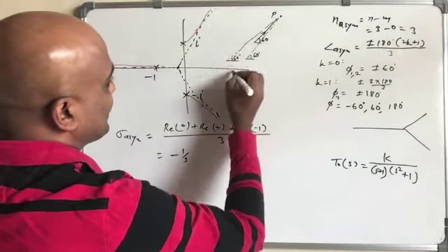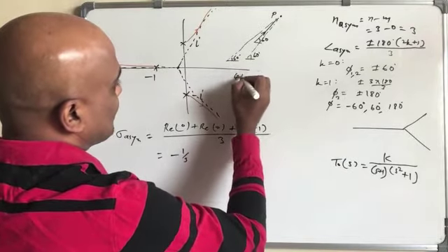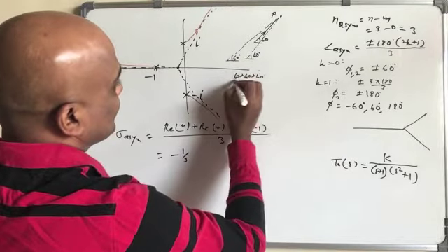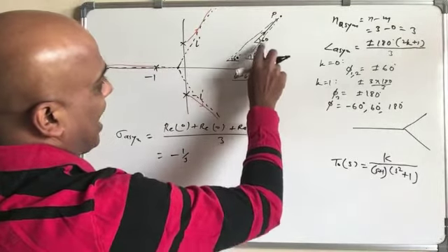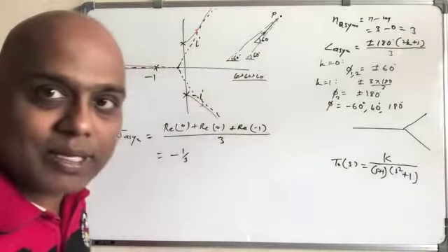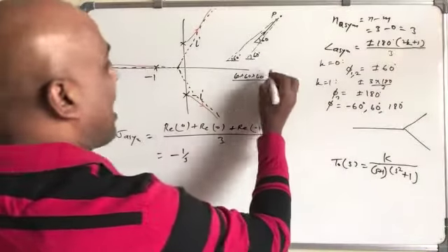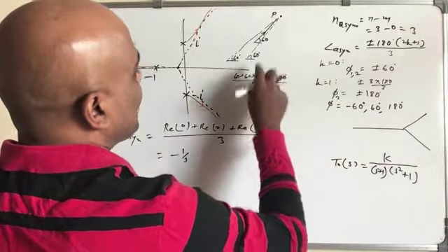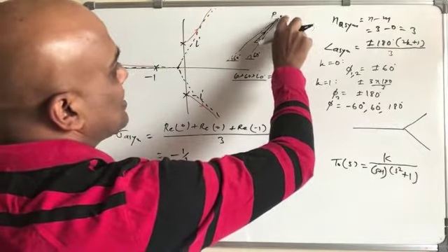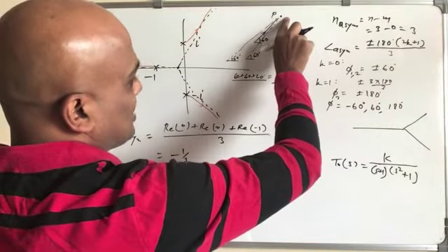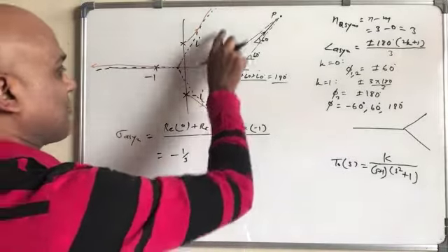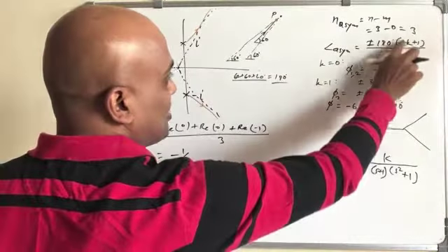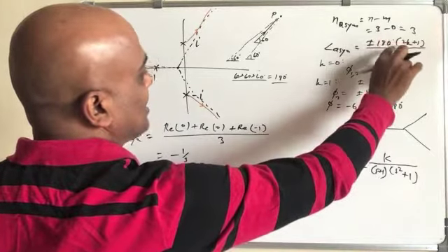So you can say 60 plus 60 plus 60. All 3 add up to 180, and this is required to equal 180 degrees. This is the requirement for a test point to be on the root locus, and hence you equally divide that 180 degrees in 3 parts.